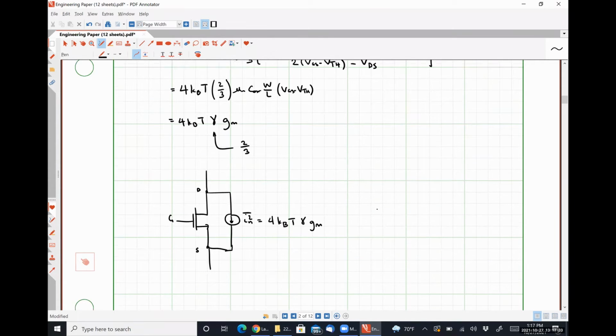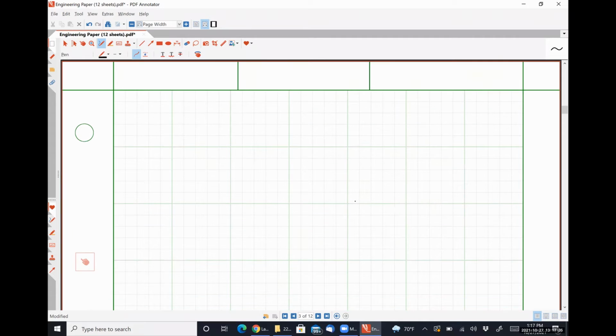So with that in mind, let's figure out what the maximum noise voltage of a transistor can be, okay? The maximum output noise occurs when the transistor sees only its own output resistance. So if we had a common source amplifier like so, and we biased it with some ideal current source I0, such that at a small signal level the transistor is only loaded by its own internal resistance, we'd have something like this, right?